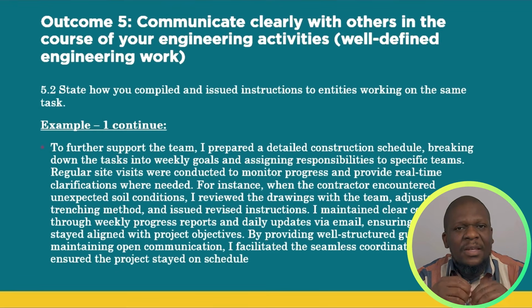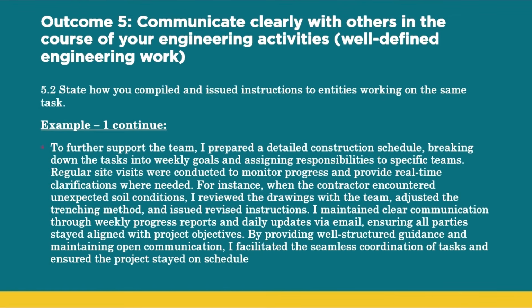Regular site visits were conducted to monitor progress and provide real-time clarification sessions. For instance, where the contractor encountered unexpected soil condition, I reviewed the drawing with the team, adjusted the necessary trench method, and issued a revised instruction. I maintained a clear communication through weekly progress meetings and daily updates via emails, ensuring that all parties stay aligned